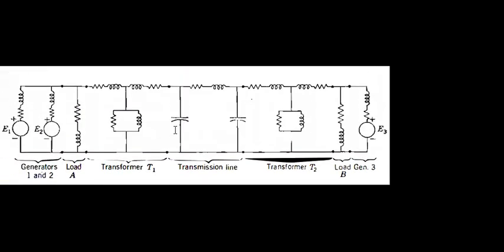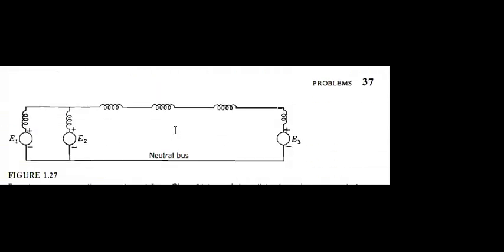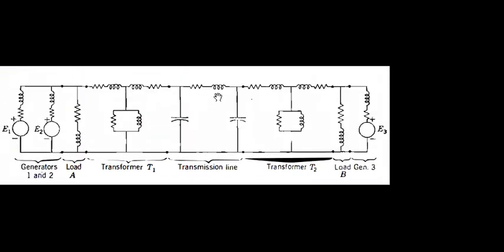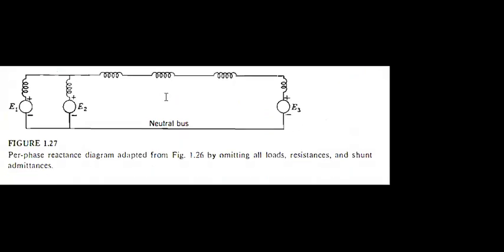Student: Sir, at the top there are three coils. Two represent transformers, what does the other coil represent? This one is the line reactance. Also the resistance and shunt admittance of the line, this part you have excluded; only the reactance part of the line we have considered. T1, T2, and this one is the line reactance. Okay. Is there any other question from your side? Okay, fine.